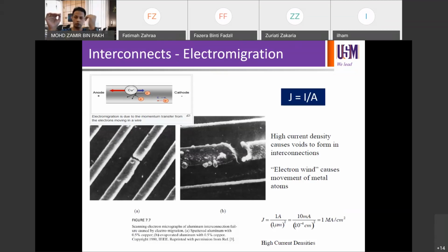So if you pass the very same amount of current over a shrinking A, then over time during electromigration evolution, you're going to pass effectively higher current density through the conductors. Because over time you will see atoms move one by one, so you technically reduce the area of your conductor, because you are left with smaller and smaller wires.